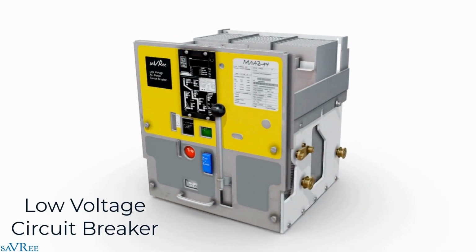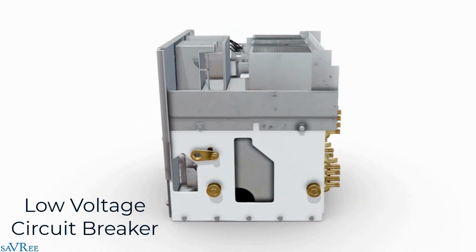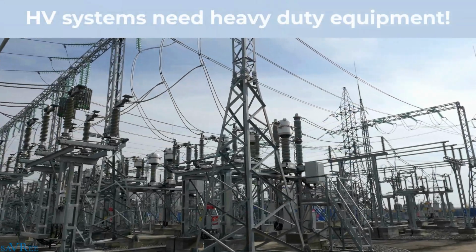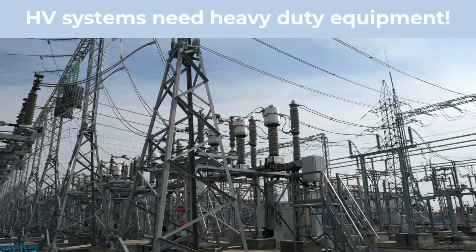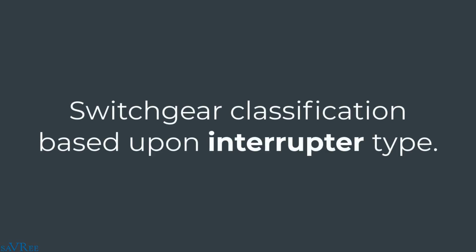Unlike in your home though, if you are working at high voltages, which typically have large current flow, that is to say a high level of amps, it is not so easy just to open the circuit. When you open a circuit at higher amps and higher voltage, you will get an electrical arc, and this arc can actually be quite large, and it may give off a lot of heat. We need to extinguish this arc as quickly as possible. Switchgear can be further classified based upon how we extinguish this electrical arc. It's quite important to extinguish the electrical arc as quickly as possible.